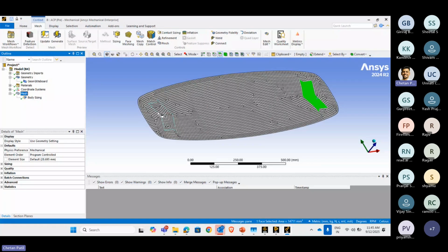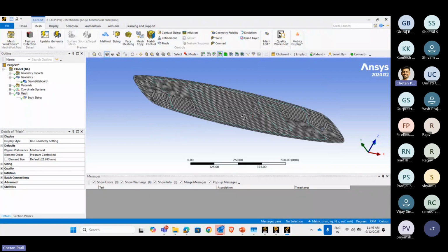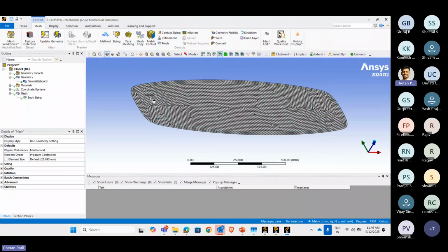You can define various different kinds of materials as well, or you can define various different thicknesses of the ply. So this can be done as an alternative process if you want to change the composition of the overall body's composite material. But as of now, we will go with the overall body being a single geometry applied with the same kind of composite material. Just the variable thickness will be applied in the thickness direction, so we don't have to worry about separations or discretizations in the model.